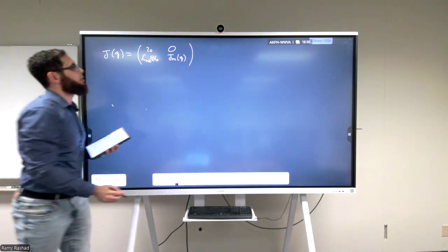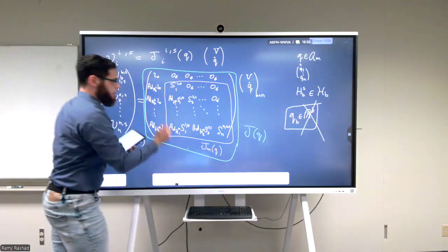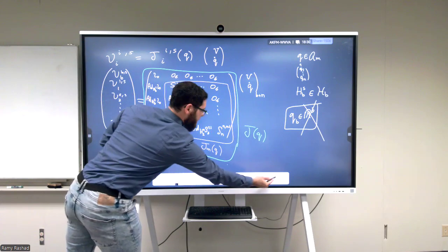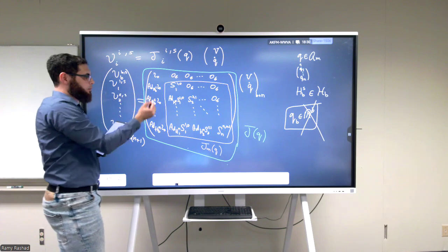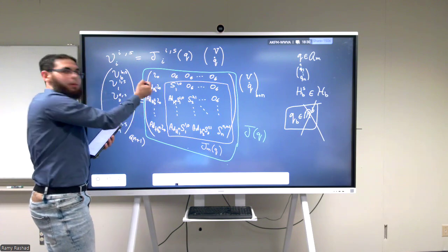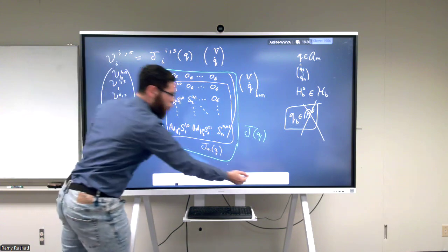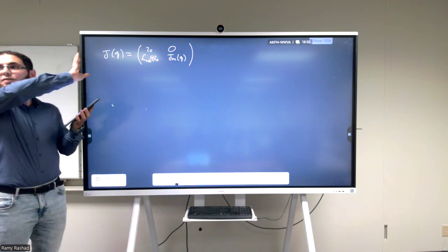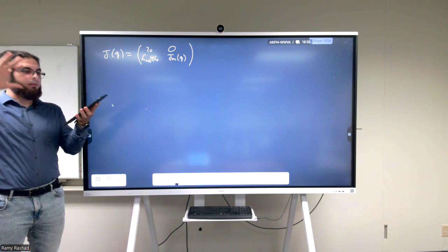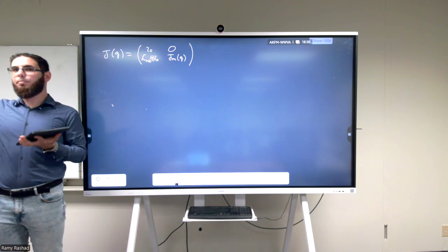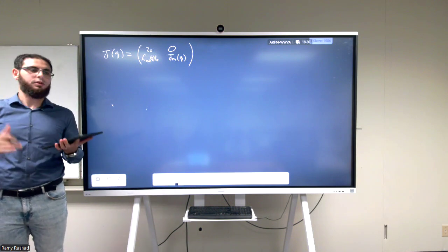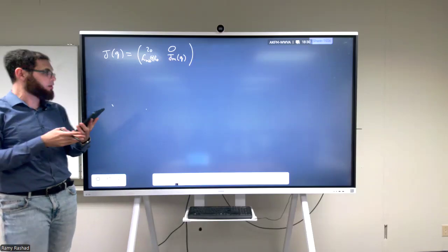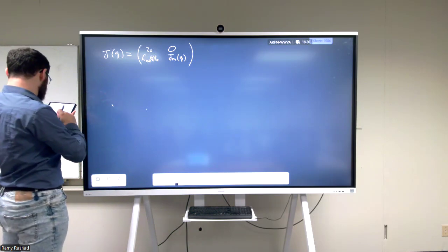So you see this part here is this purple. All of these zeros are the zero, the iota is the top left, and all of what's in here is iota multiplied by a bunch of matrices. We're going to be calling all of them M. Looks like this. But the nice thing is, because of this Jacobian, if you go back and do the same process that we did for the twists, the torques, the wrenches, the V's and the V dots, and plug all of them together, you can reach in the end an equation that looks like this.